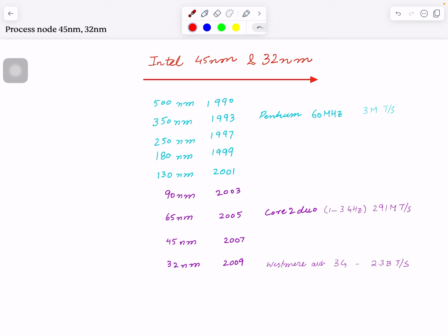So this era was a traditional kind of transistor scaling. It's called Dennard scaling. Okay, make the transistor smaller. When you make the transistor smaller, the thickness of the oxide you make smaller. And then you can adjust the threshold. You can reduce the supply voltage, increase the threshold voltage, compromise between power and delay. And net, what you get is 0.7x. You remember that factor? 0.7 is a really key factor. Transistor process technology goes down by 0.7x.